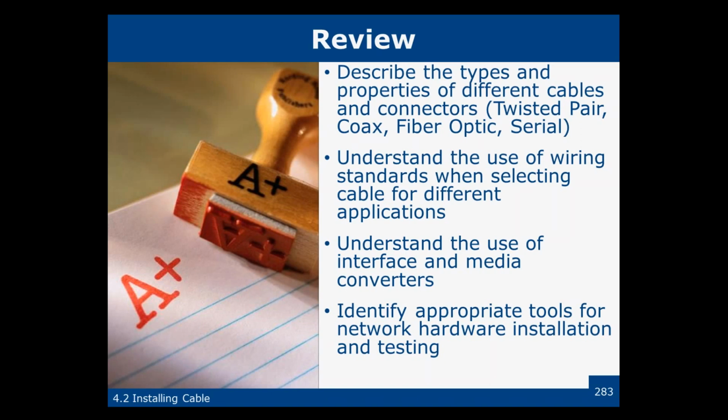So why do we use plenum rated cable in an area where building air is circulated? Is that for fire resistance? Fire resistance. Minimal amounts of smoke, and it is fire resistant. It is supposed to help put itself out. Higher combustion level.